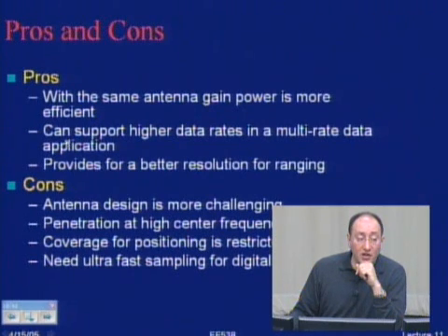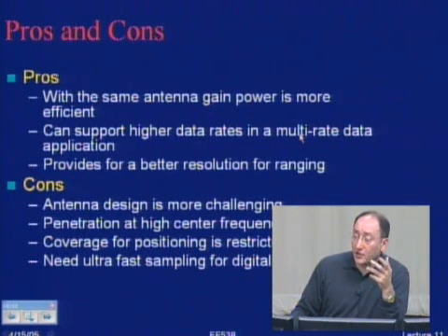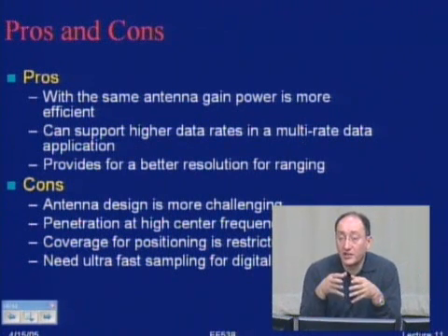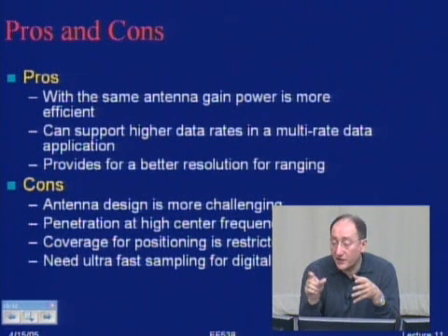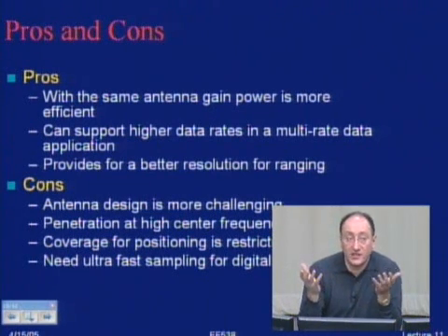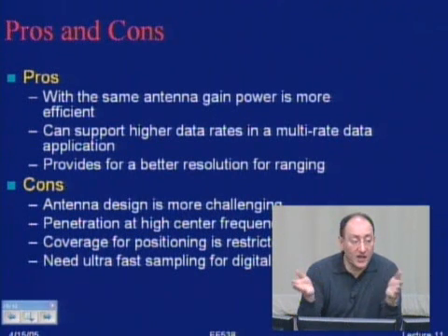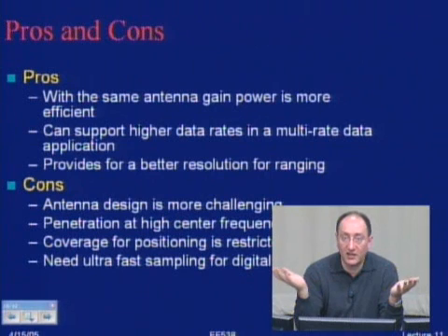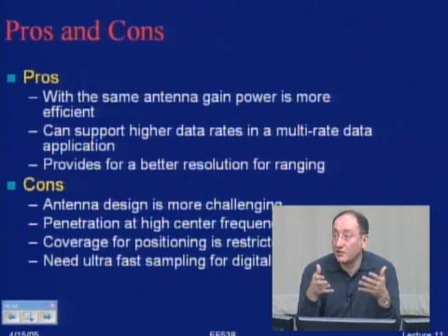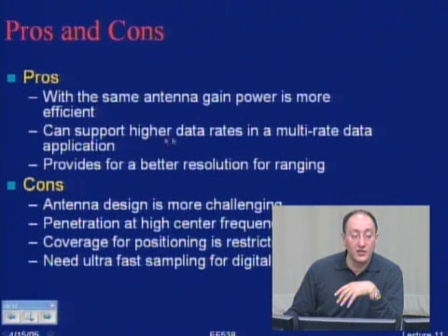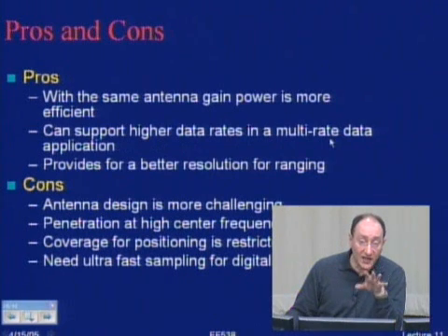The other thing that we saw for ultra wideband is that it supports higher data rates, because I have wider bandwidth. If I have wider bandwidth, especially in data communication, it's a multi-rate environment. When I'm coming very close to the transmitter, I have a perfect channel, so I can go to very high data rates. And since I have up to 1 gigahertz bandwidth, theoretically I can go to gigabit per second. So that's the second advantage. It's power efficient, I can have a multi-rate environment, and I can have very high data rates.